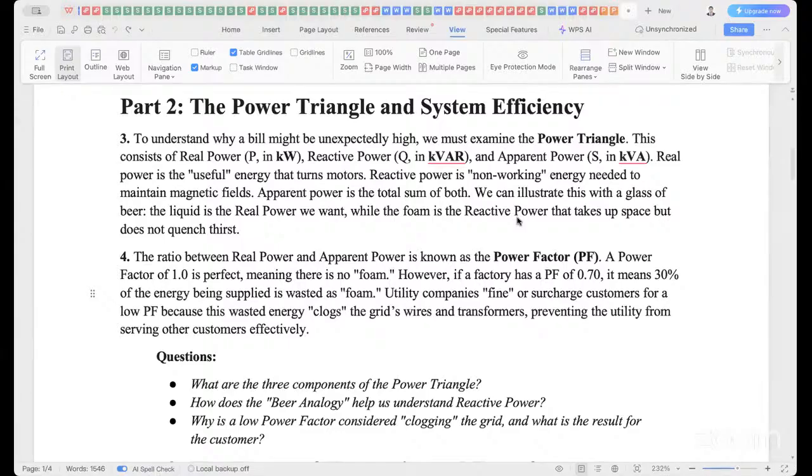But because their power factor is very poor, they have a surcharge. Sometimes on your bill there's a multiplier. If you see 1, you are not being surcharged. But sometimes you see 1.26, which means your bill will be multiplied by that to get the total amount.